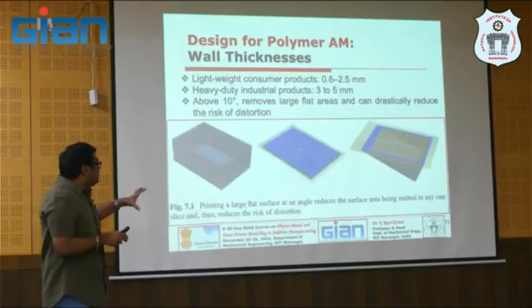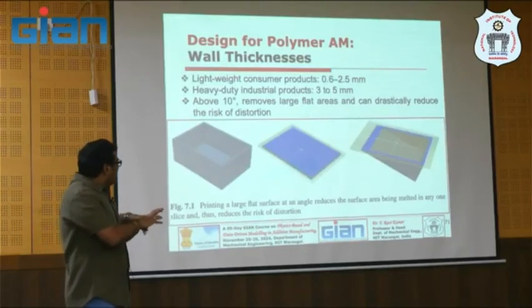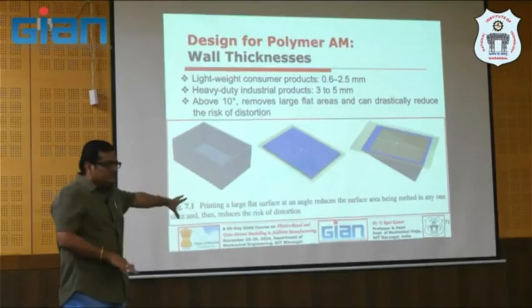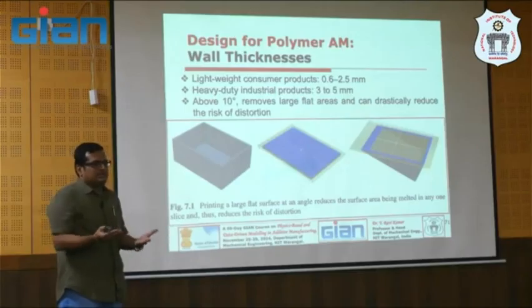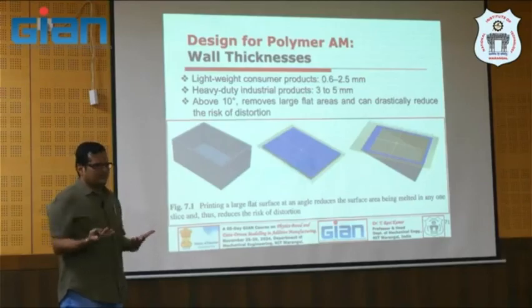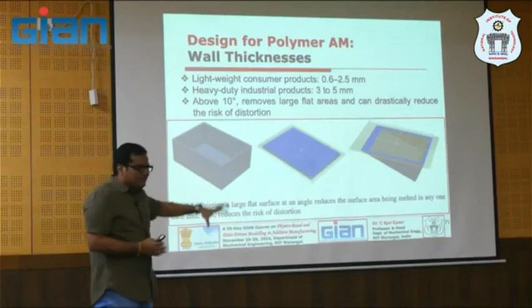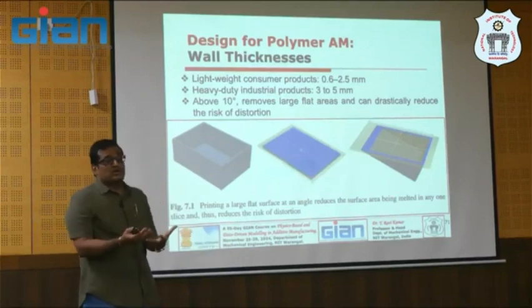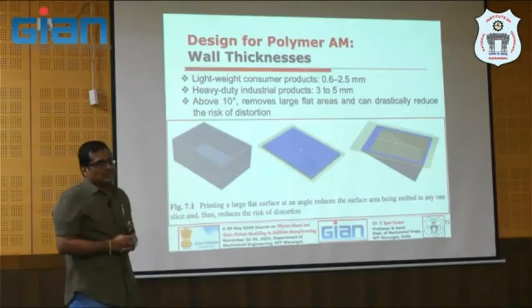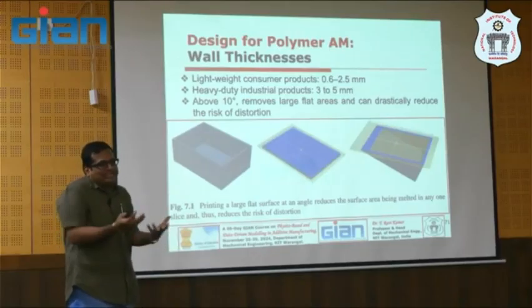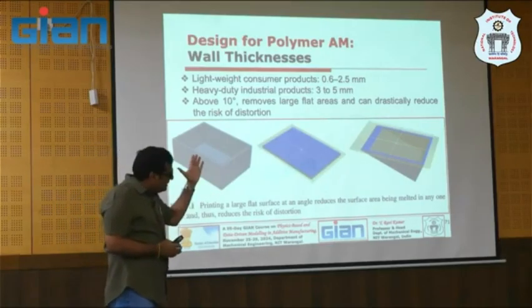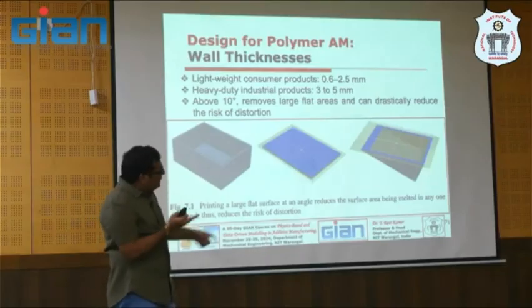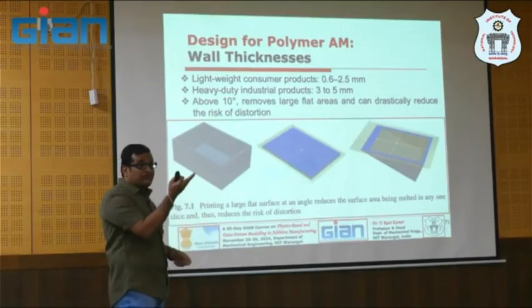Yeah, and then you have say a flat area, something like this. So always you try to minimize the bulk material. Don't allow a single layer with a bulk of mass over there, right? That is a thumb rule. Why? Because if you allow that in a single layer, you have residual stress and a temperature gradient, right? So where will the heat go, that heat dissipation may not happen properly, right? So in that case, the good idea is to make it inclined, a 10-degree inclination. So then you are distributing that into a number of layers.